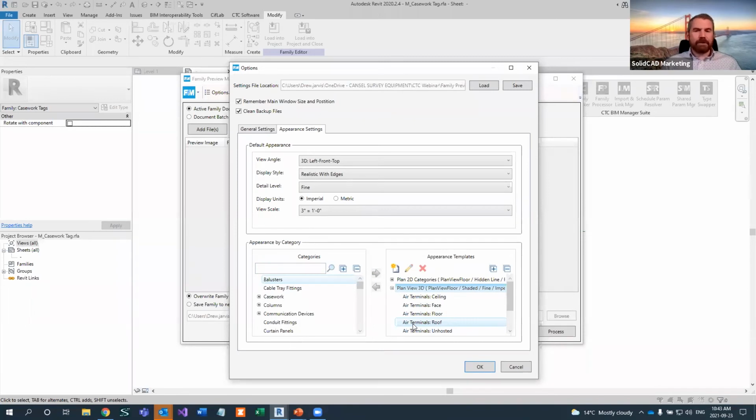That's important because let's say you had, going back to my plumbing fixtures idea, a plumbing fixture that is face-based and one that is wall-based. You'll notice when you edit those families that they're oriented differently. One of them kind of looks right where it's on the wall, and one of them kind of looks wrong where someone's taken it and flipped it 90 degrees. So picking the plan view in one and the other is going to result in a different thing, right? So you might find that different hosting is going to require different templates.